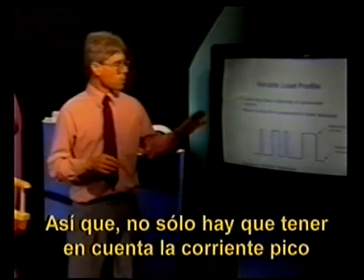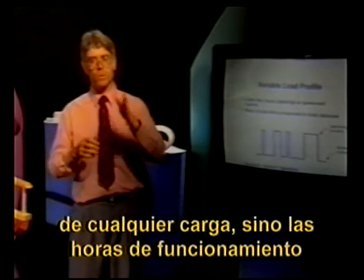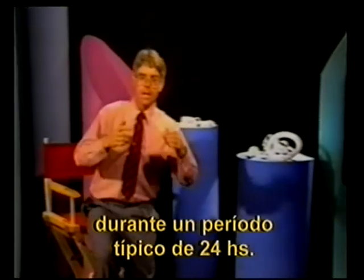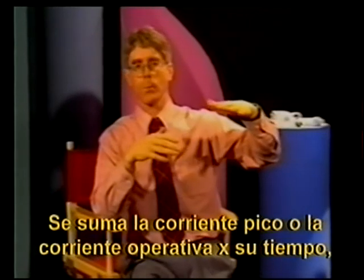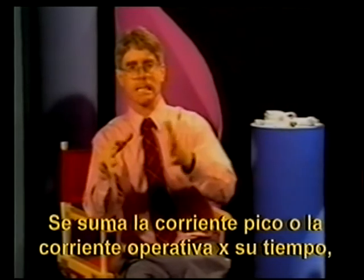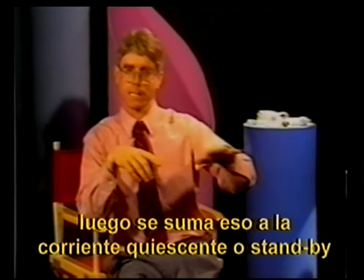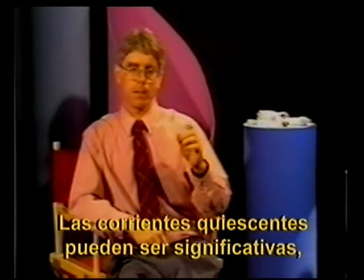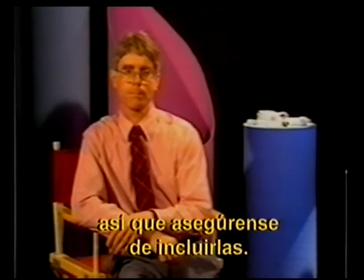So what we need to do is not only be concerned about the peak current of any load, but the hours of operation during a typical 24-hour period, and add up the peak current or the operating current times its time, and add that to the quiescent current or the standby currents that might be there, and those times. And the quiescent currents can be significant, so be careful that you include them as well.